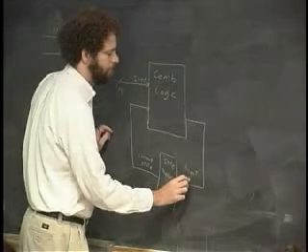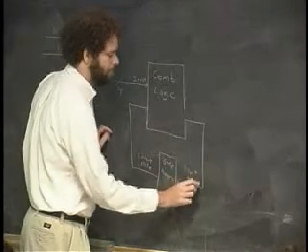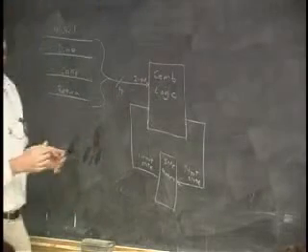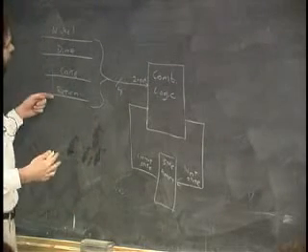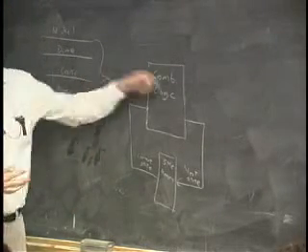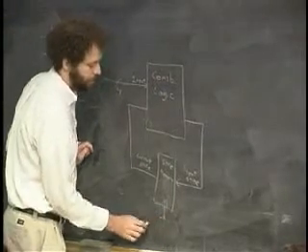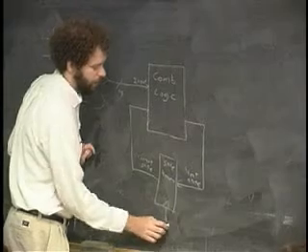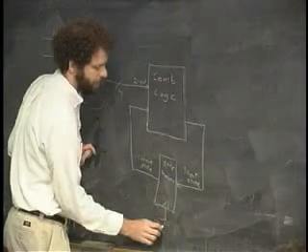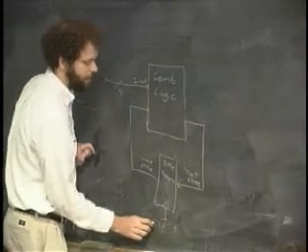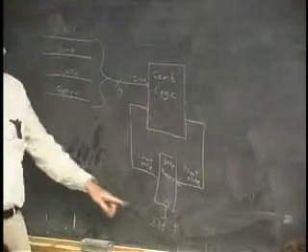Okay, so for instance, if there is a state for giving all the money back, when the return line comes in, it may say go to that state. Then this state memory in turn will be triggered by a clock signal that goes up and down, and we're going to say during the upward transitions from 0 to 1 of the clock signal is when we're going to make the transition from one state to the next.